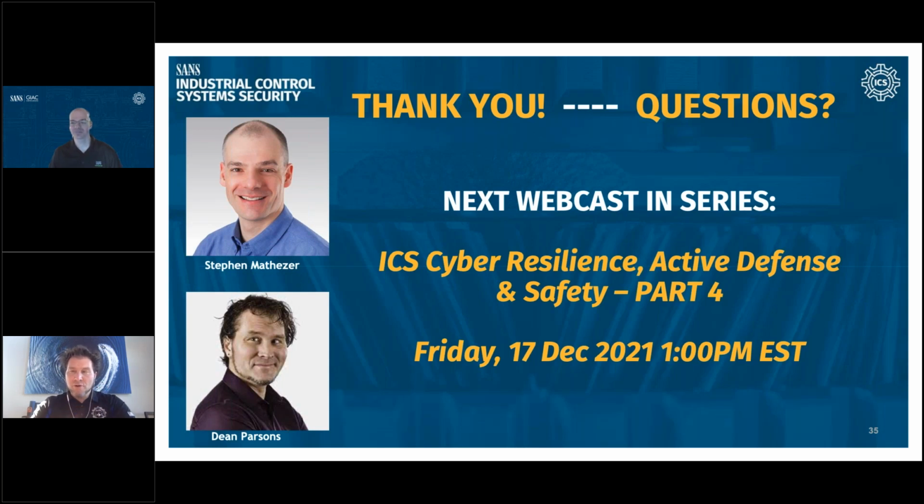One, your security folks should be inserted into the conversations for root cause analysis for the industrial control environment. So when an engineering thing goes wrong, there should be somebody from security at the table. How to determine if it's an issue with the ICS or if it's a security event is really all about knowing your environment. Do you expect someone to be on the human machine interface and click the lights out button? Is that a normal thing? Is it against your baseline? So in short, it's really all about knowing your ICS.